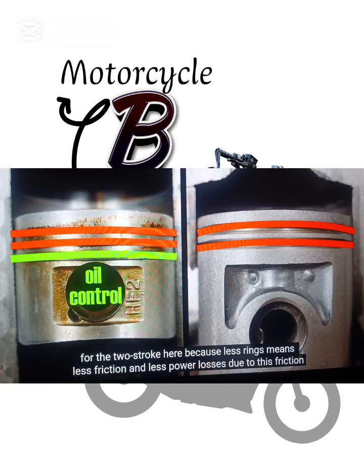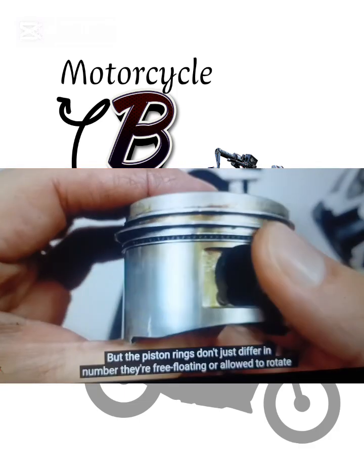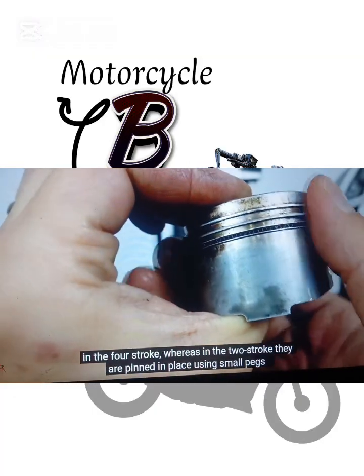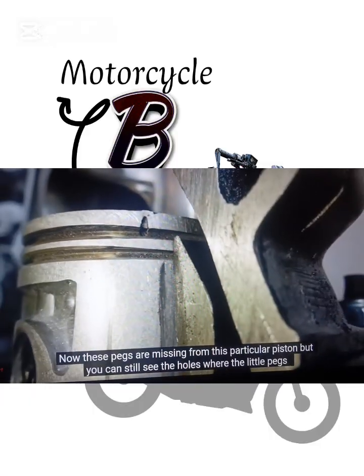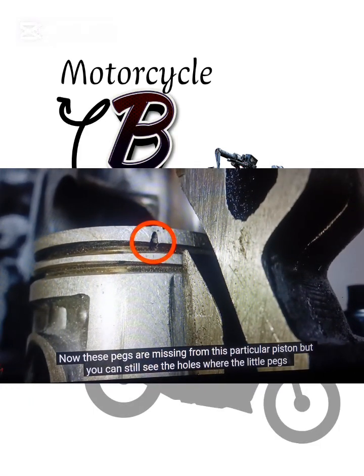But there's a benefit for the two-stroke here because fewer rings means less friction and less power losses due to this friction. But the piston rings don't just differ in number. They're free-floating, or allowed to rotate, in the four-stroke, whereas in the two-stroke they are pinned in place using small pegs. Now these pegs are missing from this particular piston, but you can still see the holes where the little pegs or locating pins go.